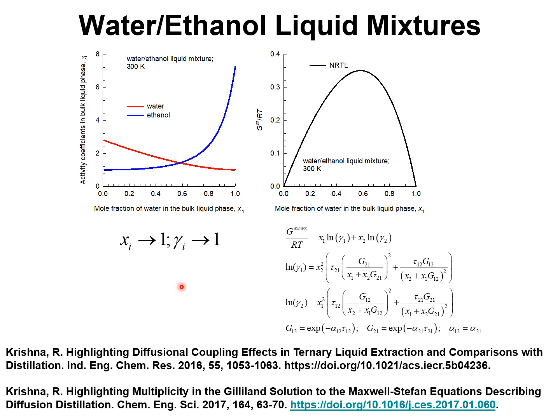Before examining water ethanol mixture adsorption in a number of zeolites, let's examine the non-idealities in water ethanol liquid mixtures. I plot here the activity coefficients of water and ethanol indicated by the red line and the blue line respectively as a function of mole fraction of water in the bulk liquid phase mixture x1.